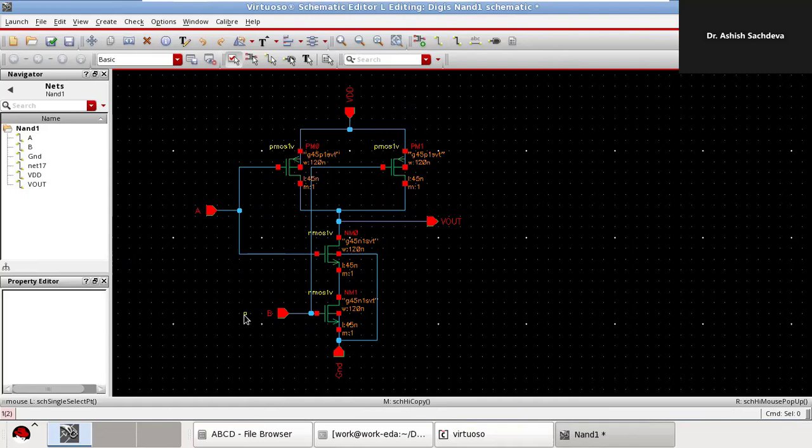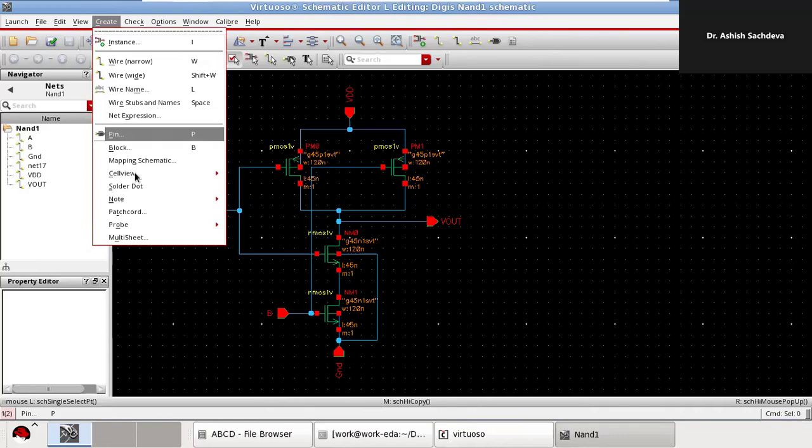If I need to run the circuit, I can have the two separate signals with the same name. But in case I need to create the symbol of the circuit, then I need to short it. Second, you should not have any ground or voltage source in the circuit. Correct? Now we'll create, check and save. We see there are no errors in this. Now we'll create the symbol.